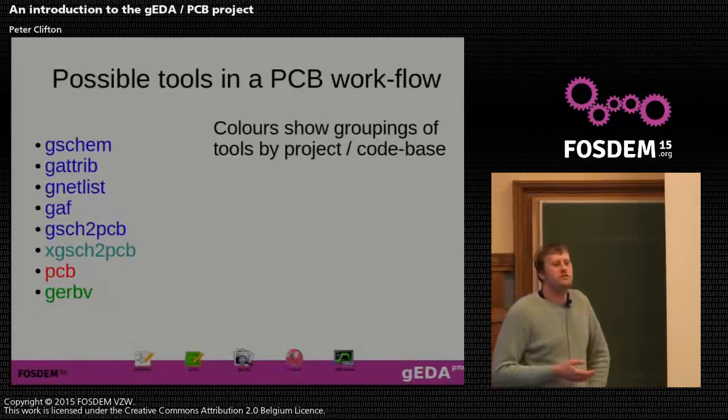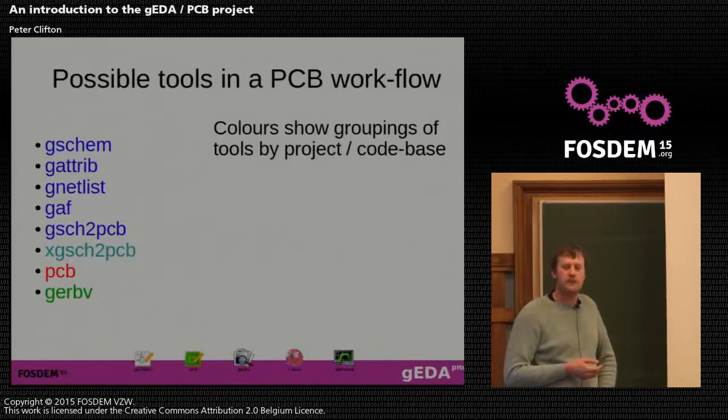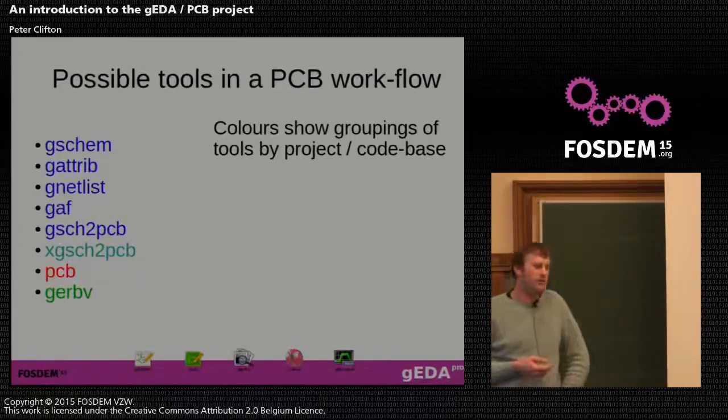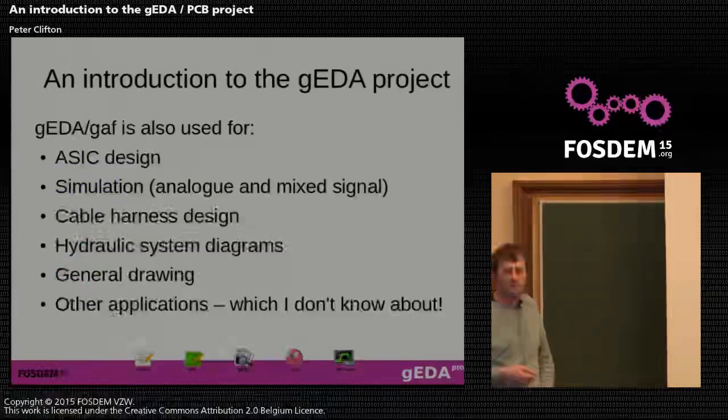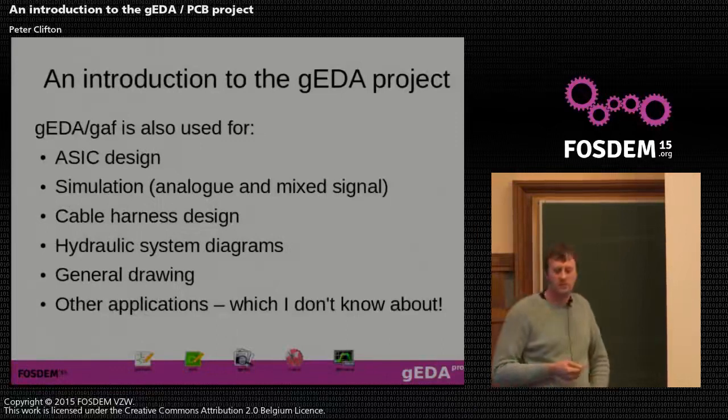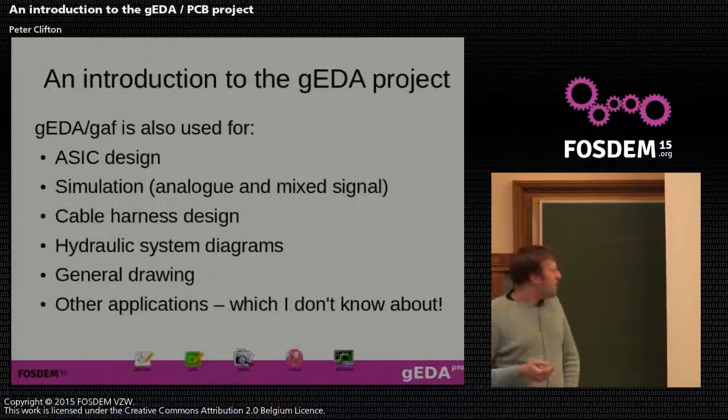GAF is also used, though, for other workflows than PCB design. We've got guys who use it for making ASICs, flying in space missions. I use it for driving netlists for producing simulations, so we can target either a SPICE-based format or a structural Verilog type format if we have Verilog simulation models. Basically I'm documenting a schematic format that drives my netlist, and if I get really diving into the details, we'll write the netlist by hand. But you can use the schematic tool for drawing almost anything.